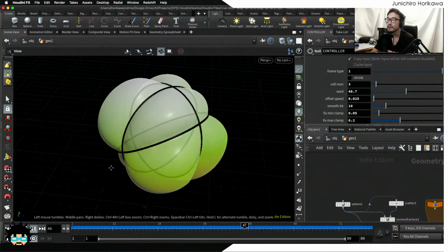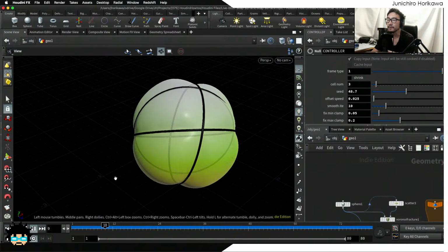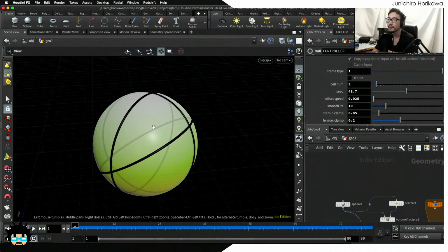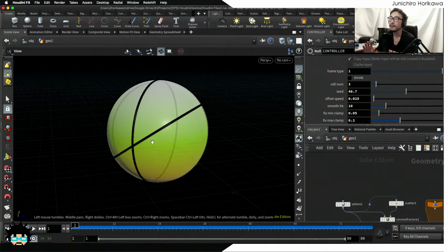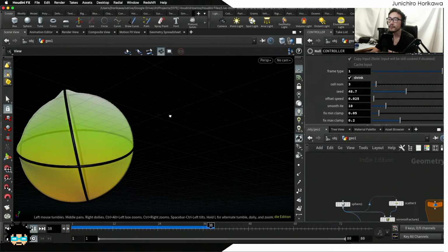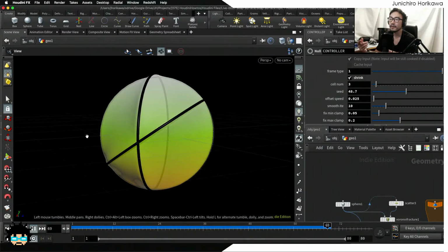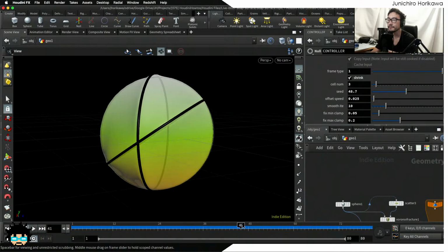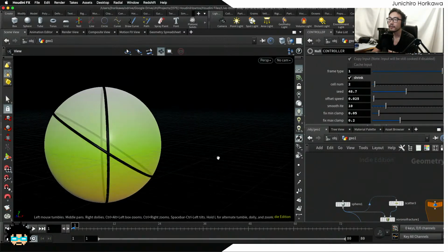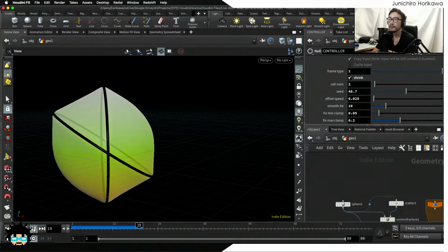And what you can do here, let me show you what you will be able to create by following the tutorial today. So this is one example, starting from a sphere, then set some constraining edges on top of the sphere. Then you can either inflate the geometry without affecting those constrained edges, or you can also try the shrinking simulations as well by clicking this shrink toggle. In that case, the geometry goes inside like a soap form, like creating a minimal surface. For that, maybe I could make a little bit less constrained edges and see how it goes. So something like this.